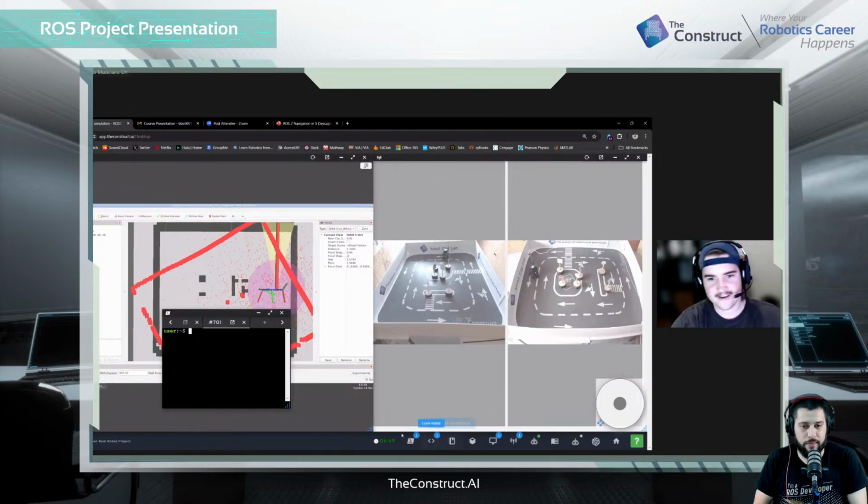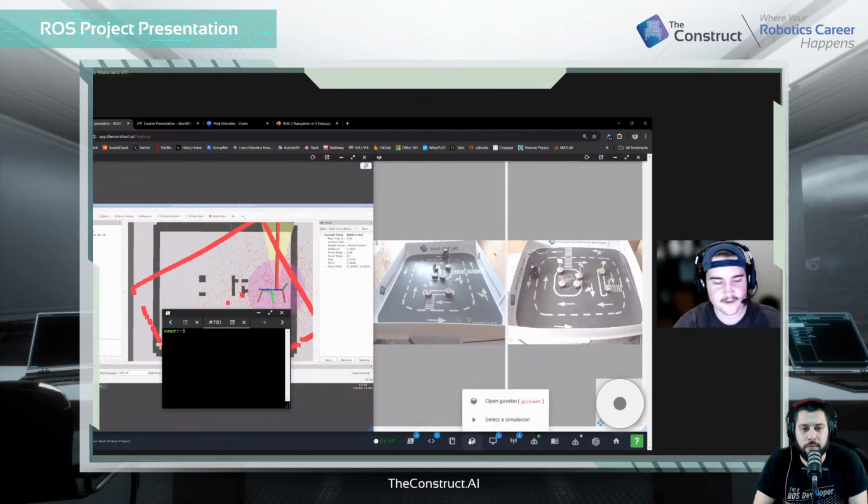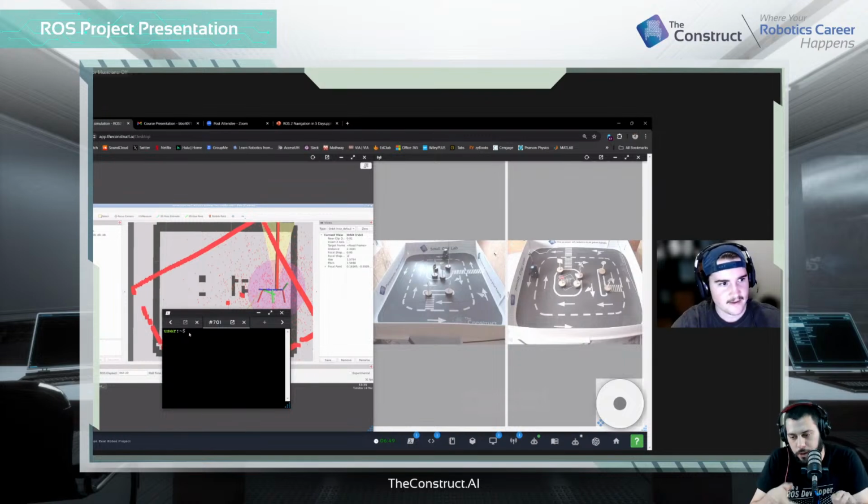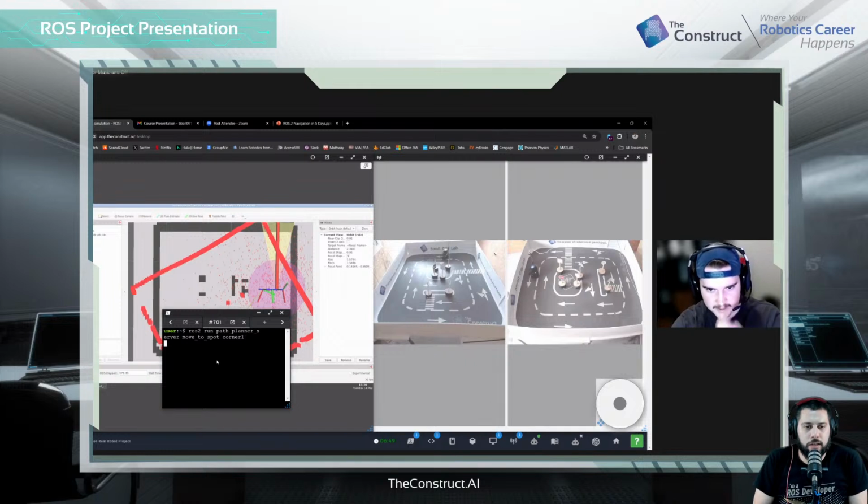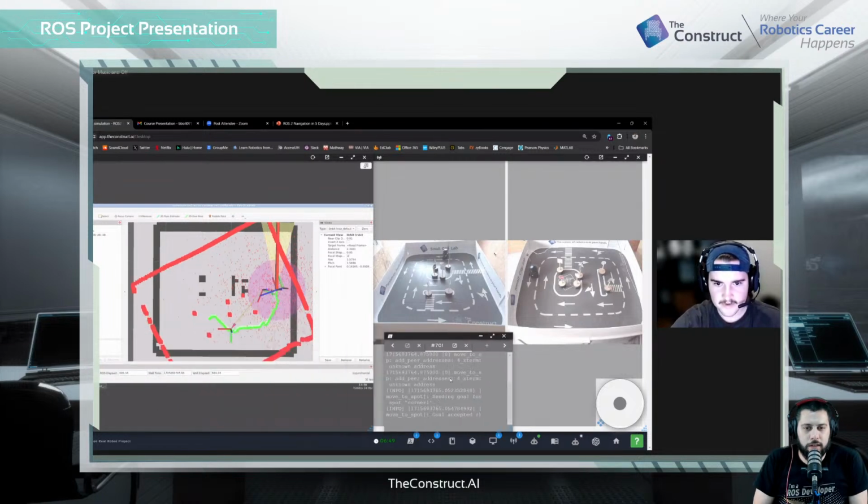Okay, I see. Yeah, because like I said, it still does the obstacle avoidance fine, but it just never shows them on RViz. If you were actually to do ROS2 topic echo of your global cost map, you would just see the numbers, because it's the message in there. It's just RViz can't see it for some reason. Okay, I see. Alrighty, so I'm gonna move to corner one first, and we will see.